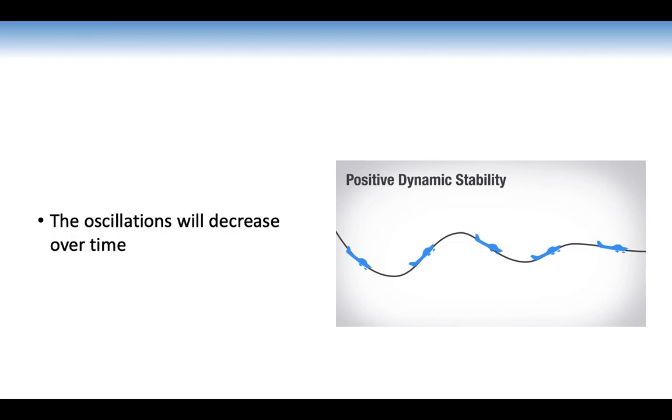So positive dynamic stability. If you look through oscillations, remember dynamic relates to movement. The oscillations will decrease over time. And our airplane does demonstrate positive dynamic stability, and I'll show you that in the training area in flight.